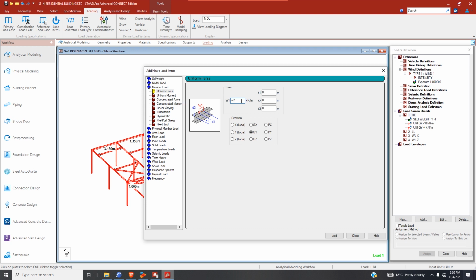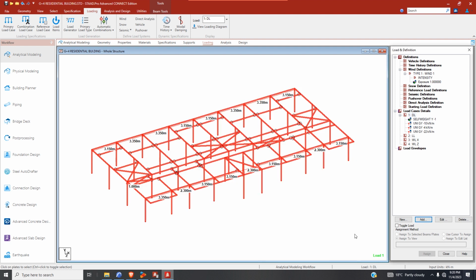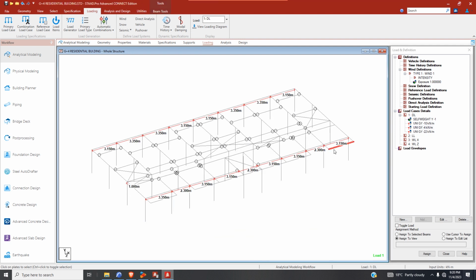This one is a primary beam because although this node has intersected, it breaks the beam here. This beam from this point is one beam. So we're not going to release any because this one is primary beam because it's connected by column at both ends.